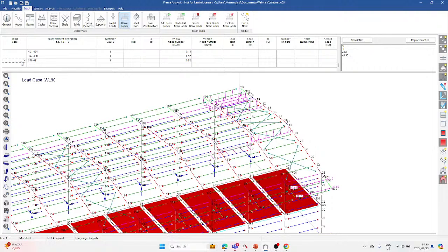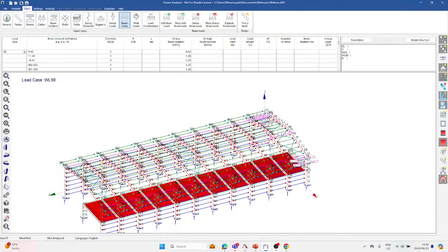and then let's block copy, so that we can apply the loads throughout the purlins that we have selected to apply loads on. So it's from B1, yes, until B30. So it's 1 to 30. Number of extra is going to be 10. Then node increment 33.